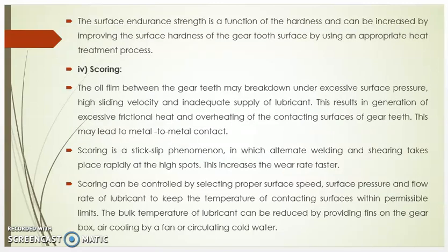The surface endurance strength is a function of the hardness and can be increased by improving the surface hardness of the gear tooth surface by using an appropriate heat treatment process. Now last, that is scoring.